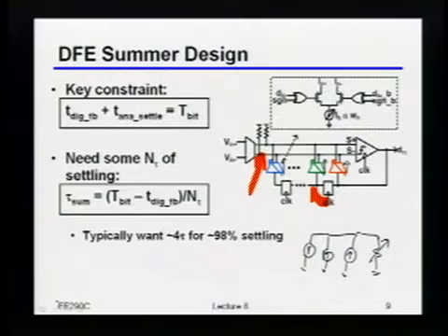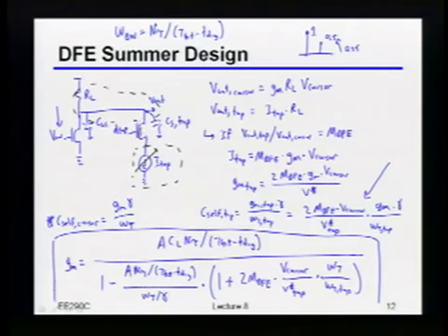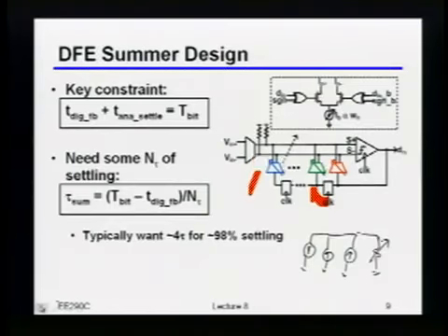Question. If you keep the switches in saturation, why do you have nonlinearity? Because their RO is not infinite. Which RO are you talking about? Just the RO of the current steering switch of this device, right? Or are you just saying the nonlinearity from the GM and RO of the transistor?